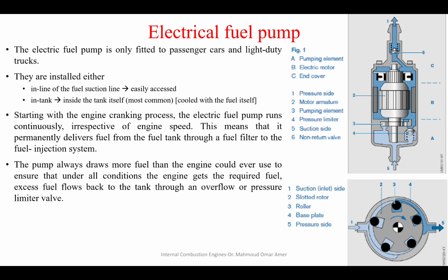Because we know the high pressure pump, any fluid that is compressed, what happens to its temperature? Increases. Okay? And the high pressure pumps, where are they installed? They are installed on the engine, very near to the engine. So they suffer from the high heat from the engine. So the extra fuel drawn by the electric fuel supply pump helps cooling the high pressure pump.